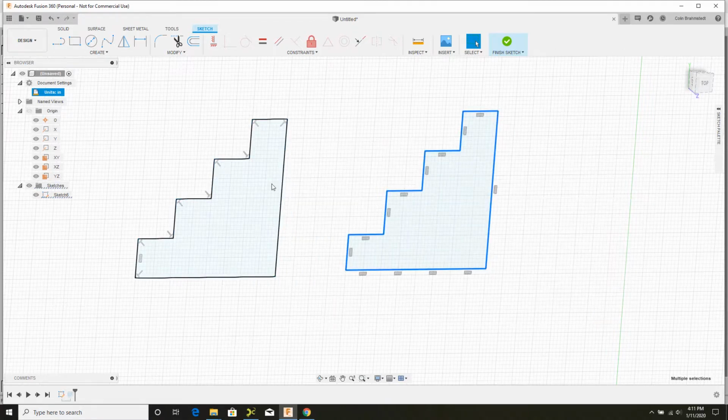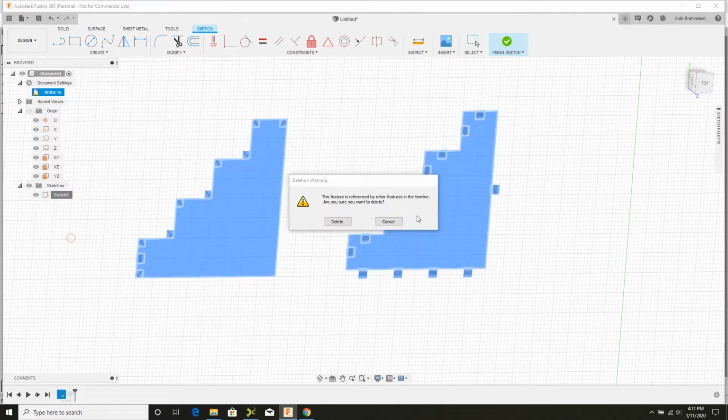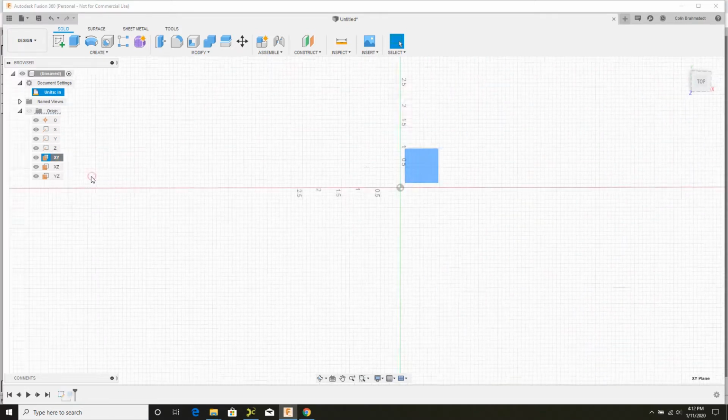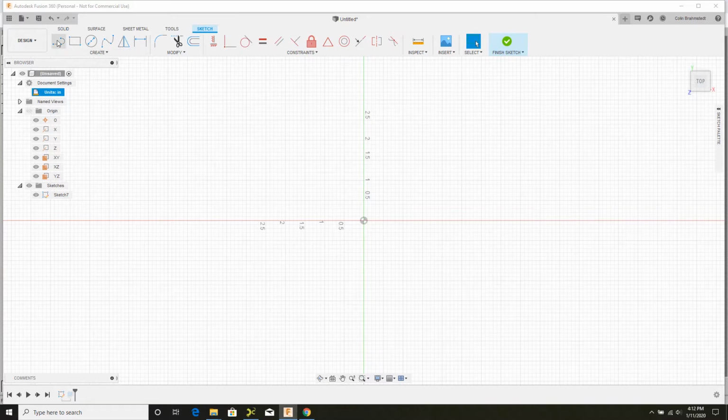And just mess around with things in 2D, right? So I'm going to close out of a sketch, delete. We'll go over what sketches are later, but for right now, if you pick a plane like, say, XY, create sketch. You're going to see these sketches and create tools. Just mess around. Just create circles and primitives and stuff and build up on that.